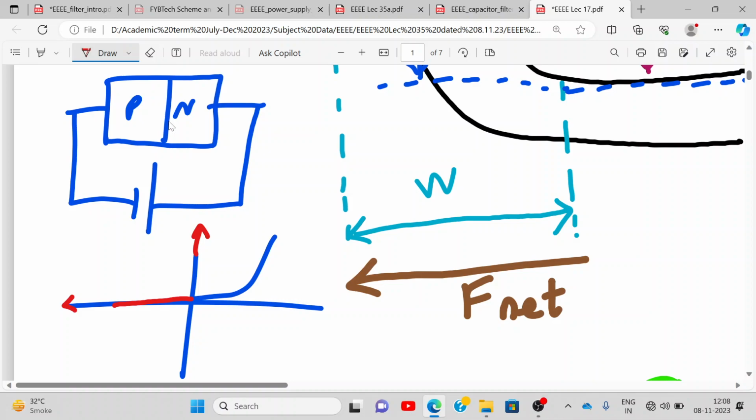All right. But let's say this voltage is 20. So let's say someone has given you a task to keep on increasing the value of reverse voltage. So this reverse voltage, let's call it VR. Currently VR is 20 volt, minus 20 volt basically. So it didn't do anything. Your reverse saturation current was flowing. Now, whoever was operating has gone back. He doesn't understand the meaning of increasing incrementally. He has increased suddenly from 20 to 50. Still, you don't get any significant current. You get only a constant current over here.